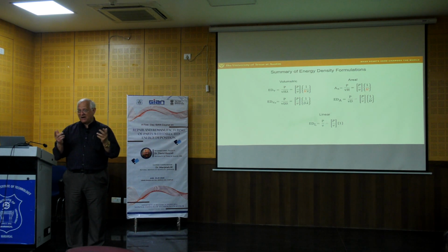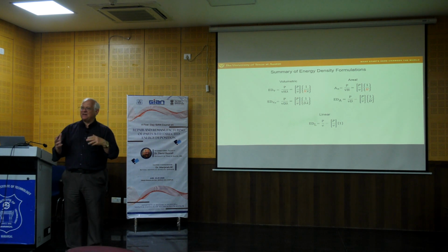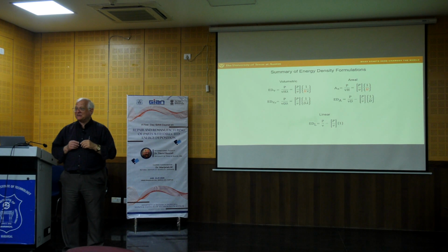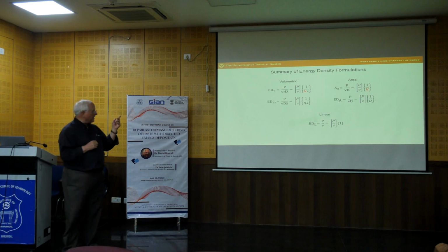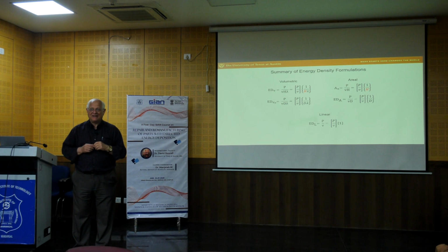D is pretty constant. The layer thickness lambda is also rarely changed. It's more or less constant. And so if I don't mess with the hatch spacing, then all of these will give the same answer if H, D, and lambda are constant and I'm only affecting the power and the velocity. So it doesn't matter which one we use, they all give good results.